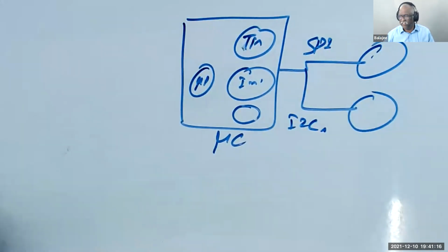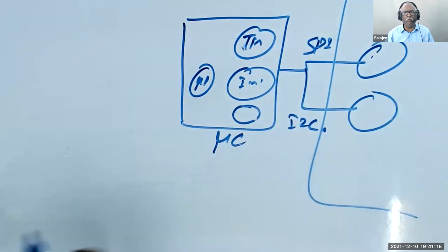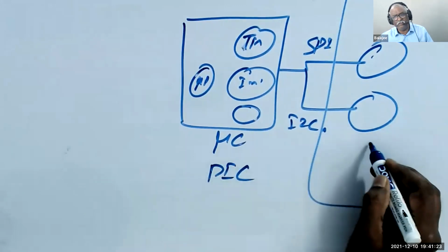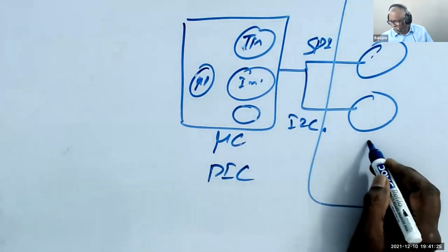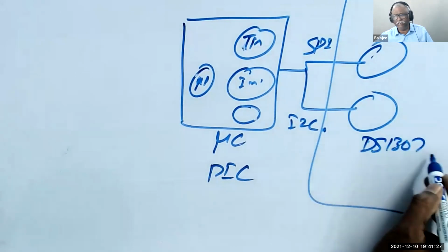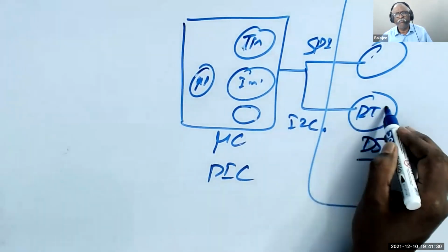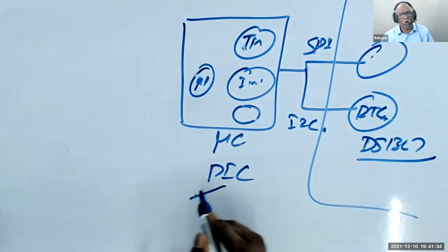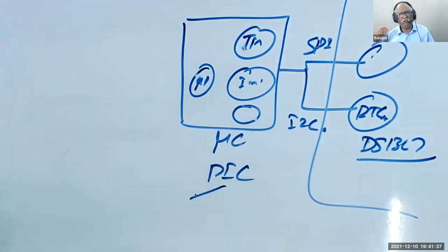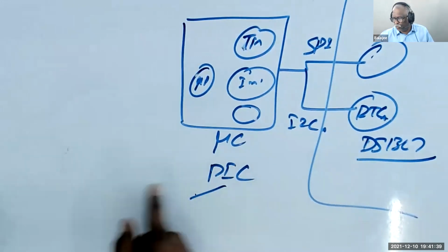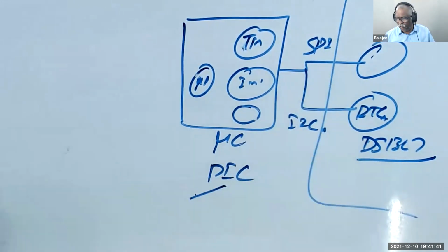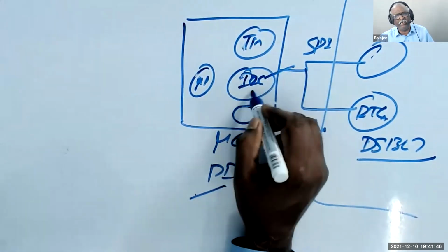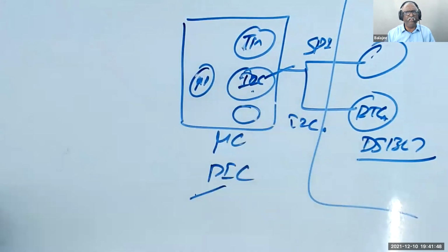The beauty is, this is much easier. If you write code on PIC for the DS1307, that is the RTC chip, the same code you have written on PIC will work on ARM. It will work on everybody. The only thing that will vary is how to talk to the I2C, because the I2C controller inside the microcontroller is different, and that's also easy.